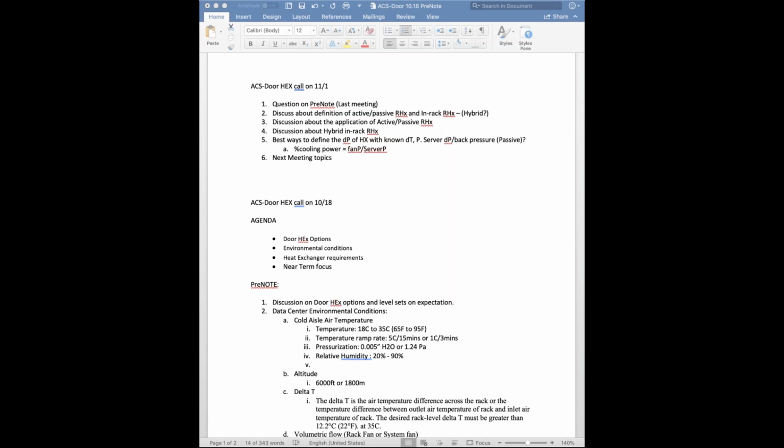Yeah, I agree with you. I think that traditional air cooling is going to make sense, to your point, economically, unless we're getting to compaction of around 30 to 45 kilowatts per rack. And then I think you'll find when you crunch the numbers that it's going to be more economical to deal with the excess heat using a rear door versus a traditional air handling unit. Yeah, so that's a good example to talk about, and something pretty relevant for us.